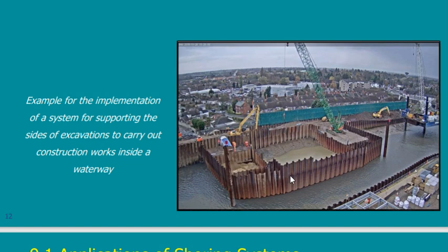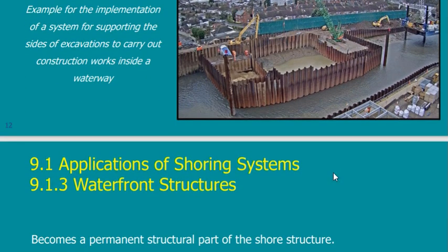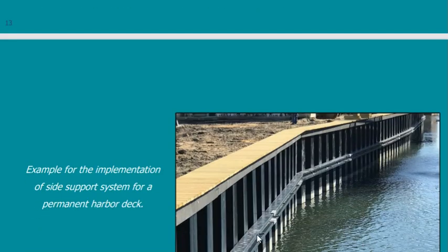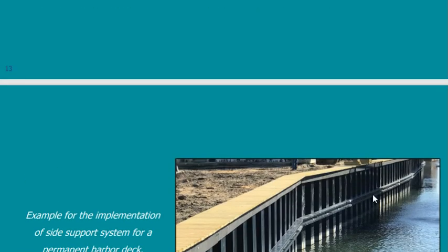Usually I do not use steel to be permanent below water because it will rust with time. So what happens is that in some cases, something like this, it is more or less similar to a deck, a harbor, marina. So in this harbor, they want to construct a wall. So they have done this. This may be, by the way, steel, but in this case, it will require additional precaution.